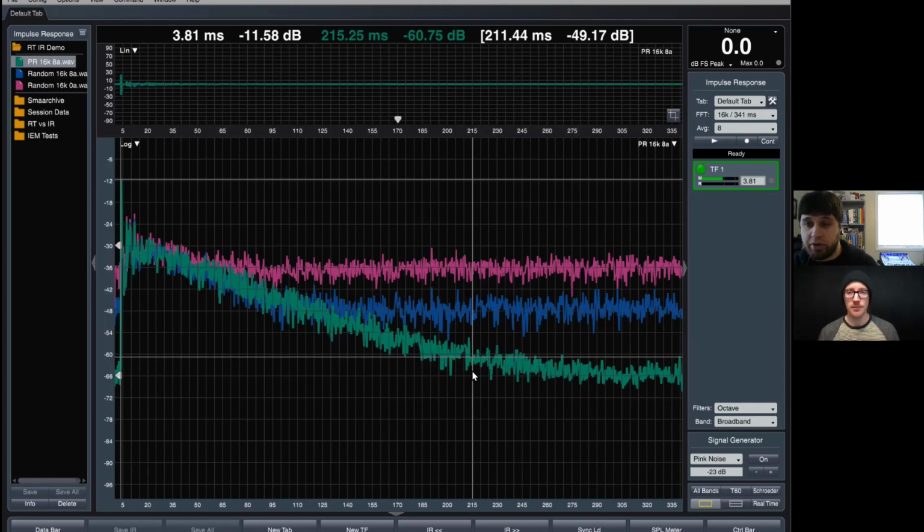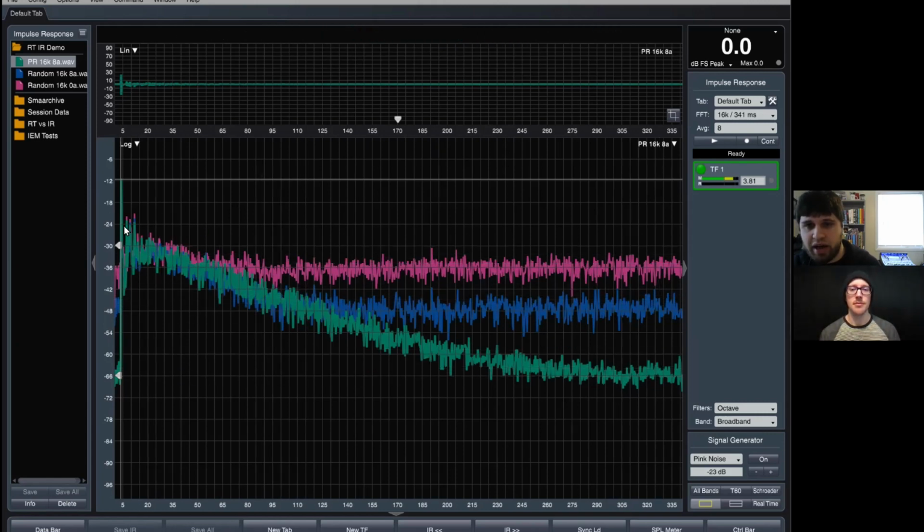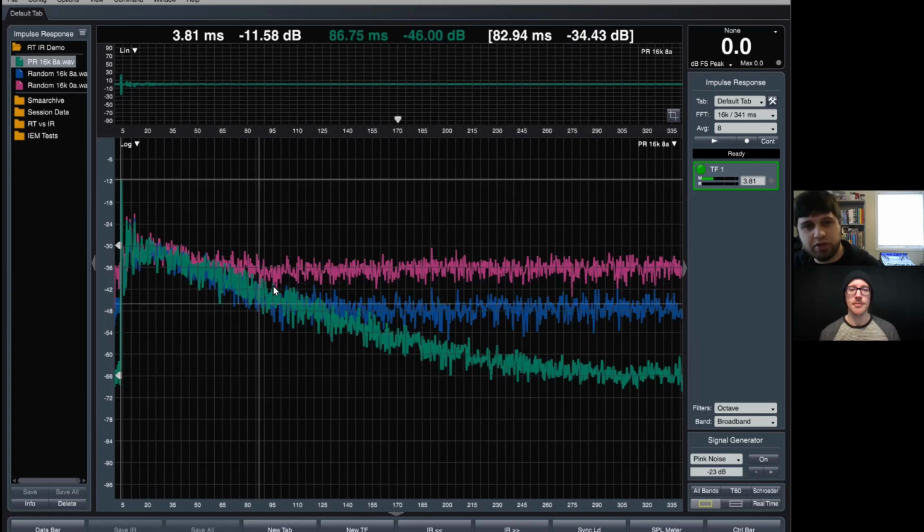But if we're acousticians and we want to characterize the reverberance of a space, and I'm hitting the noise floor only 30 dB down, that doesn't give me a whole lot to go on, right? Whereas if I can push that noise floor down, I'm exposing more of the reverberant qualities of the space, and I can do that more accurately.